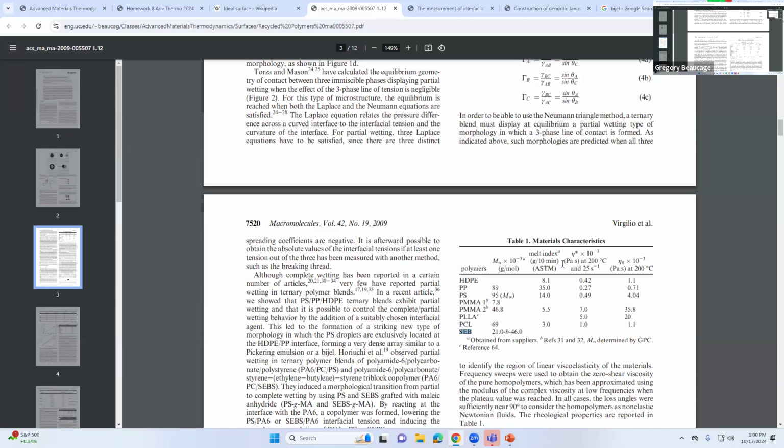Then there's a trail over. And one over that shear rate is this relaxation time for the spaghetti, the time constant associated with the spaghetti transitioning from being straightened out to going back. At this rate, the time related to that is slow enough that the things can relax. Then down here, you get a Newtonian viscosity. Newtonian means it's constant. This number is a constant in that equation. It doesn't depend on the shear rate.